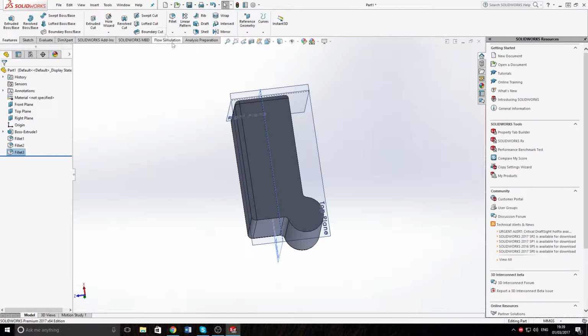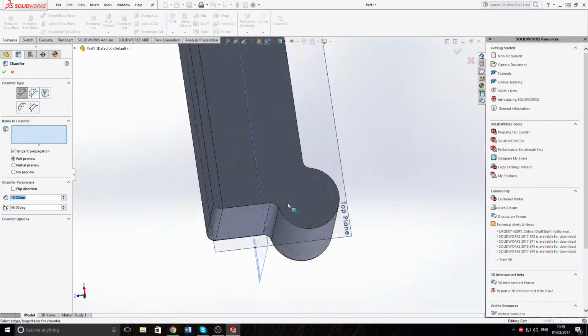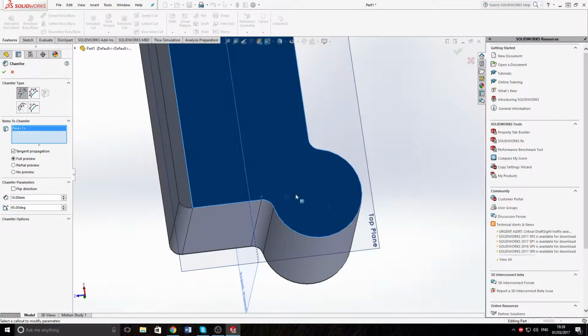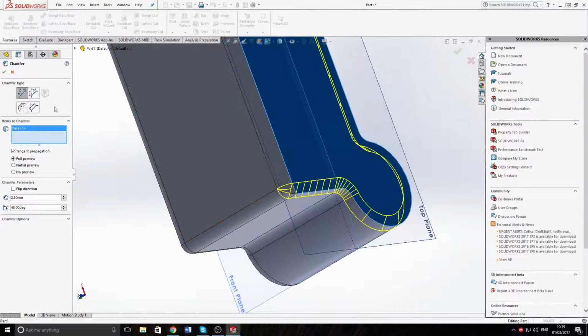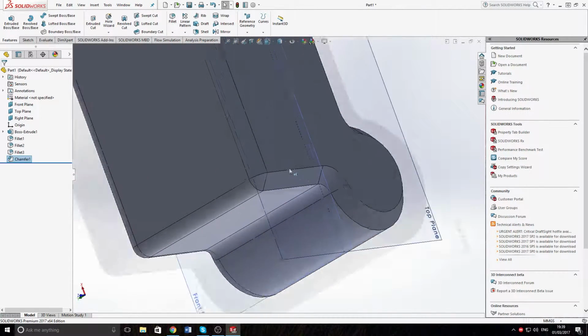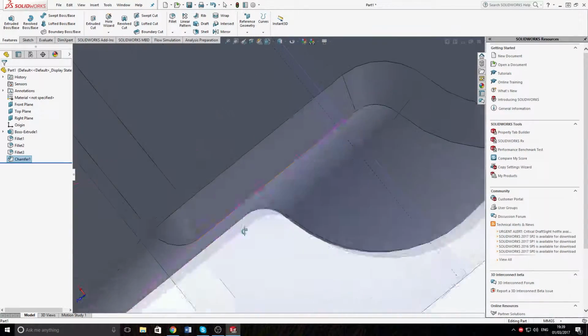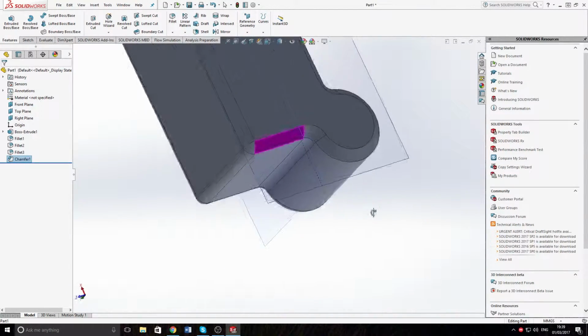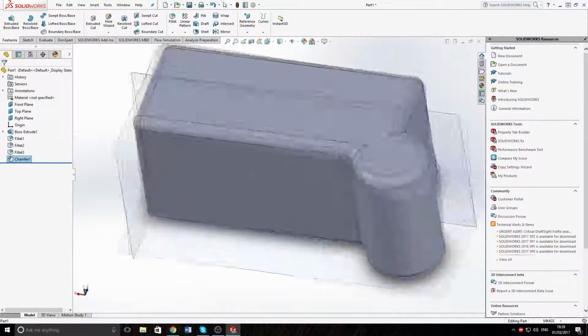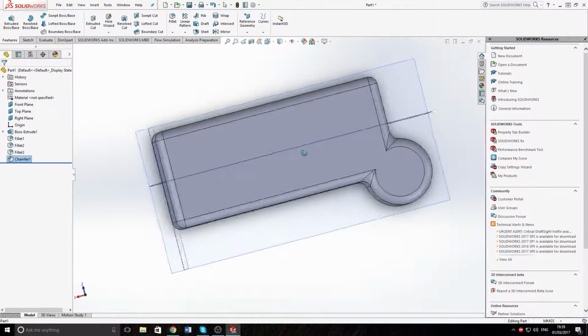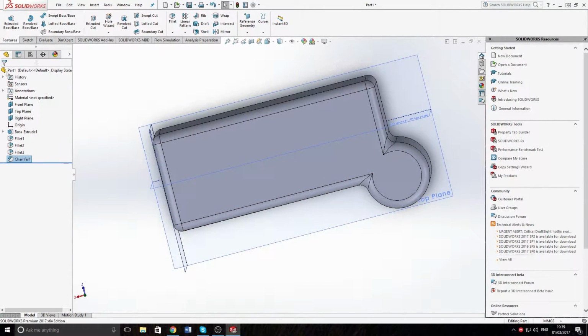If you click on the down arrow here, you'll get the option for chamfers. These are just straight angle cuts. So say we do another 2.5, and accept that, and accept. You can see that it's just a 45. You can change angles and do loads of other stuff.